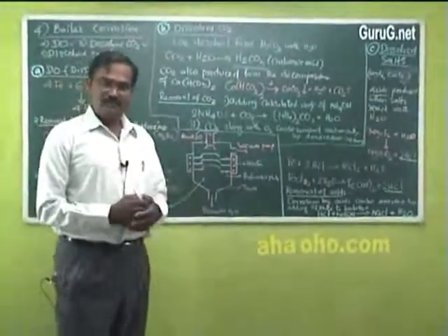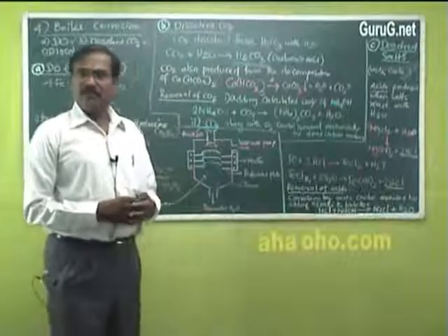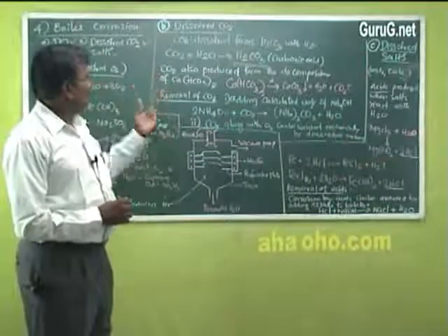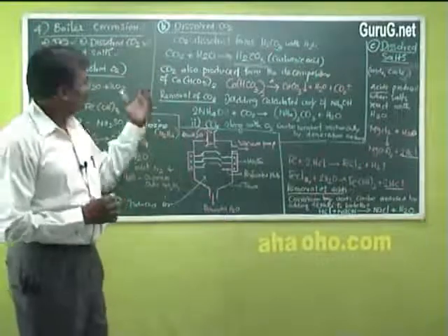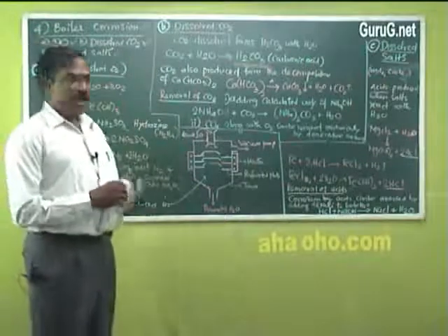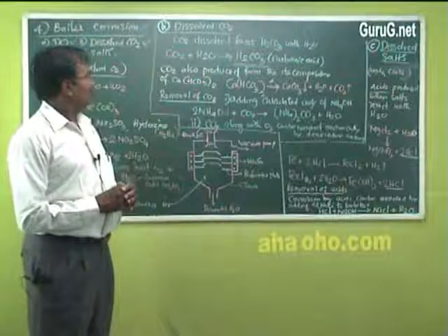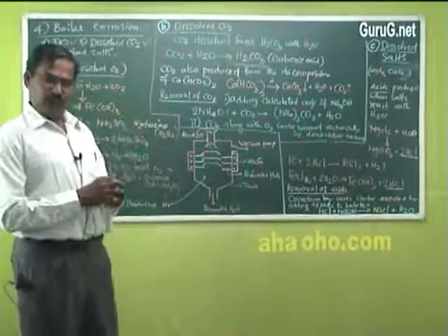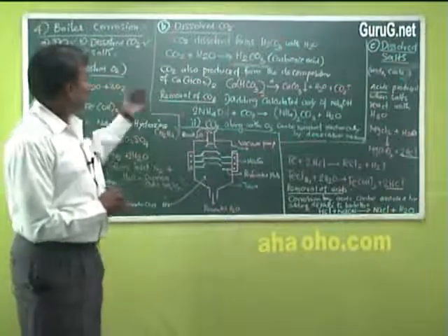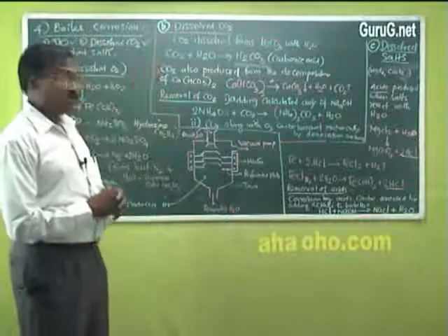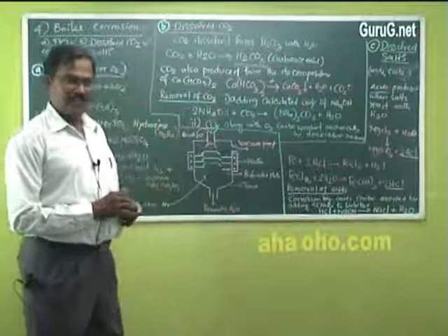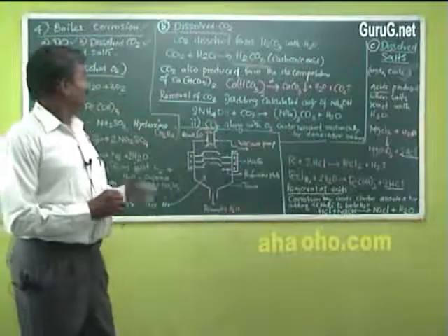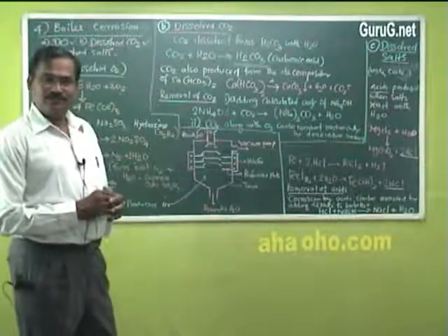Any acid on contact with the metal leads to corrosion, so carbonic acid is also responsible for that. And this carbon dioxide, which is present in dissolved form, that is one thing. And carbon dioxide is produced by the other source, that is calcium bicarbonate, which is present in hot water.